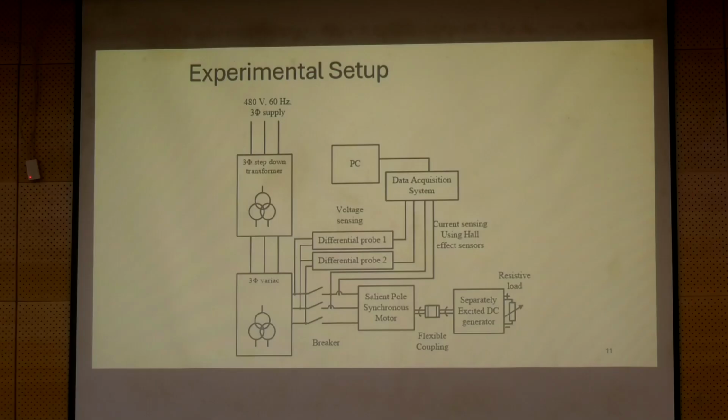So you still need this expert knowledge to check whether you have a sinusoidal looking wave, three-phase waves that are equally spaced. One of the common mistakes I made while I collected data was that the current probes are direction sensitive. If you put it in one orientation, you will get one.